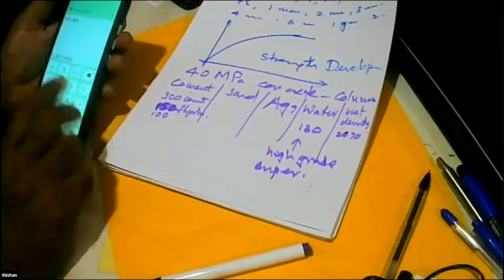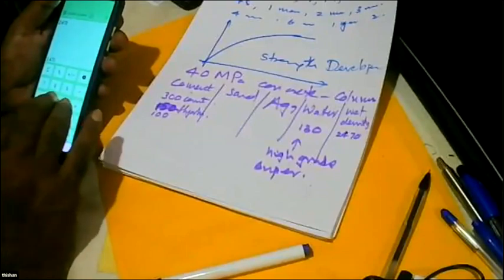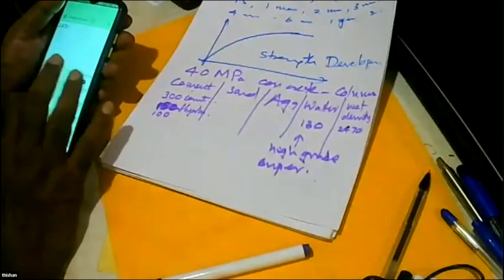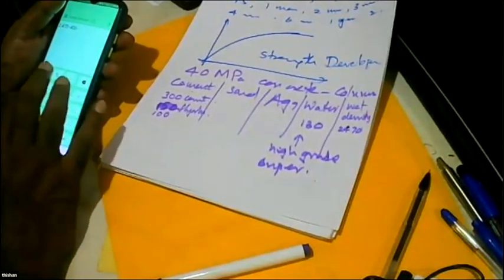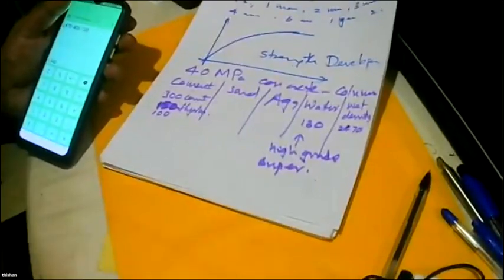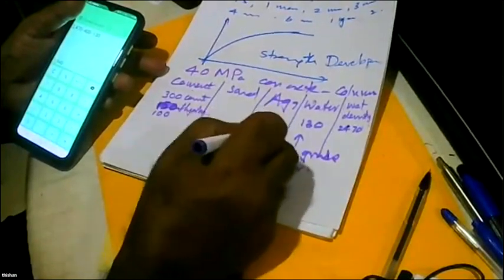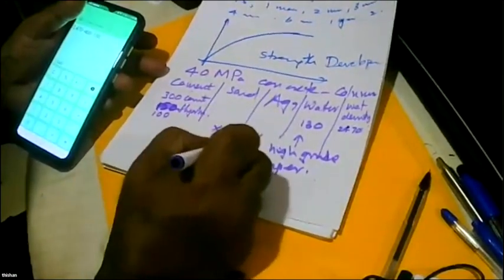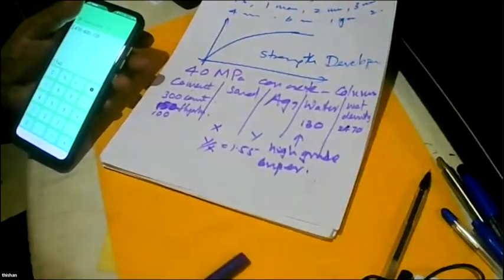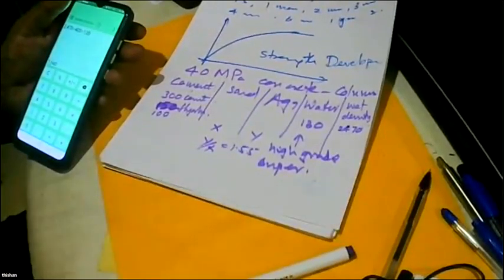Now I'm going to look at numbers. 2470 minus 400 minus 130. Now this is in a column, so I have to pump. So I'm going to use Y over X ratio as 1.5. I like to get high strength also, so I don't like to use too much sand. I like a little less sand, but at the same time I'm a little restricted.